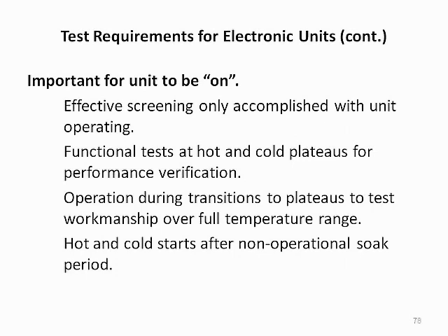When conducting thermal vacuum tests, it is important for units to be on because effective screening is only accomplished when the unit is operating. Functional tests must be performed at hot and cold plateaus for performance verification. Operation during transitions to plateaus is required to test workmanship over the full temperature range. Hot and cold starts should also be performed after a brief soak period with the unit turned off.